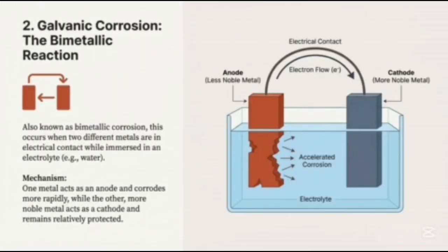The second type of corrosion is galvanic corrosion, which occurs when two materials, one acting as the anode and the other as the cathode, are placed together in an electrically conductive solution, also known as an electrolyte solution. One material loses electrons while the other gains them, resulting in corrosion in the material that loses electrons.